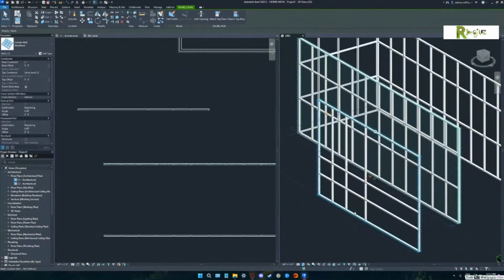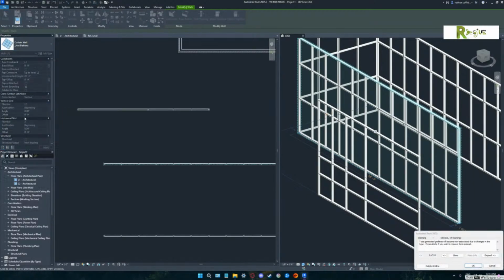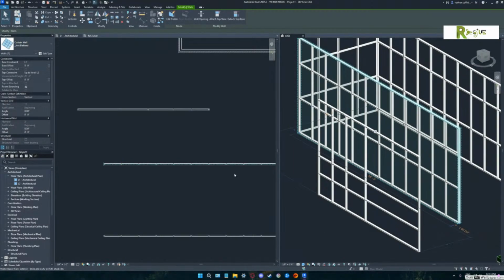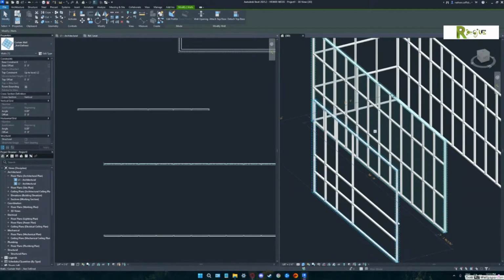Select the wall that's behind it. This one. Yep. Pick that one. Now go to the properties and not an edit type. I just want you to change this curtain wall from curtain wall to the not defined one. When it does, it's going to ask you a question and you just say okay. Don't say delete the grid lines. See, that's released all of those locks that have been put on there. So now I don't have to build this separately.